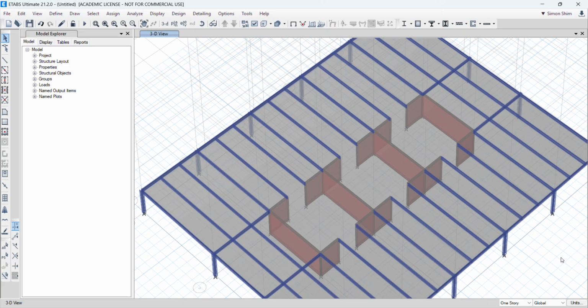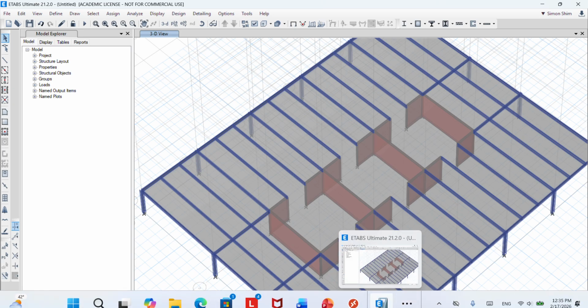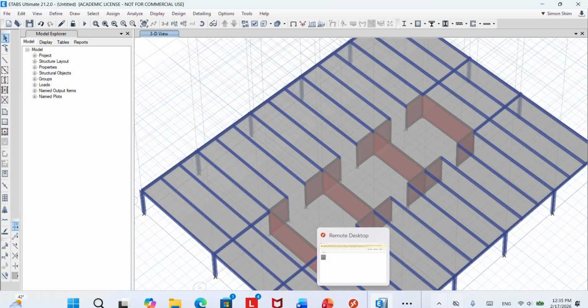So we have 15 minutes. Let's set it up. We just finished the geometry, but there is one thing I'd like to add because it is our general practice. Because this is a concrete wall, concrete zone, the construction team is typically going to erect the concrete wall first, ahead, and eventually this wall needs a concrete beam.